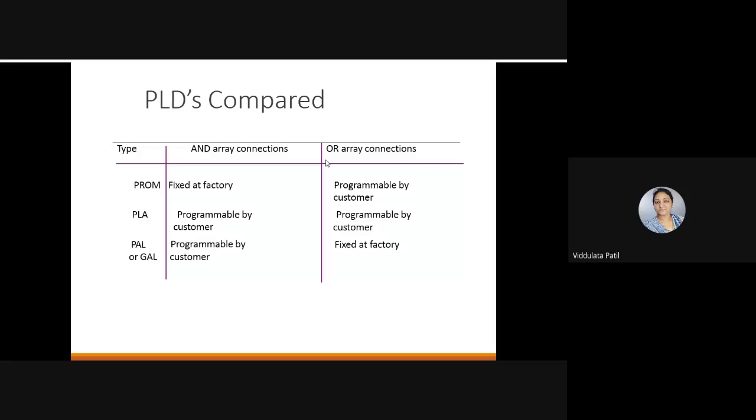Now, if we are comparing these PLDs, starting with the simple programmable logic devices, the first type is the PROM, that means programmable read-only memory. In this type of PLD, the AND array connection is fixed at the factory. That means the user cannot change these connections, but the user can program the OR array connections. So whatever changes he wants to make should be done at the OR array connection.